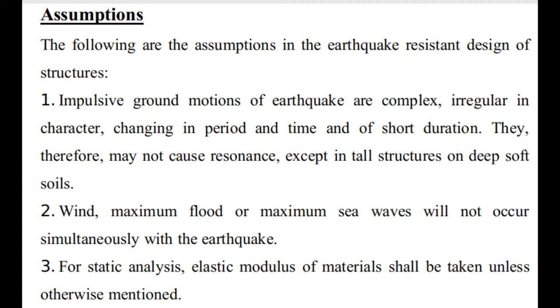Second assumption is that while the earthquake is taking place, simultaneously there is no wind force, no maximum flood or maximum sea wave occurring. Number three, for static analysis, we will see just after a few minutes or in my next video the static analysis and the dynamic analysis in detail. So for static analysis, elastic modulus of the material shall be taken unless otherwise mentioned. So these are the assumptions for the earthquake resistant design of structure.